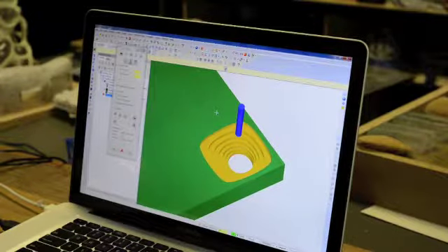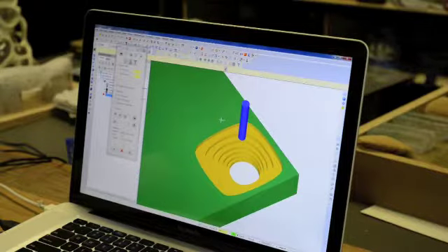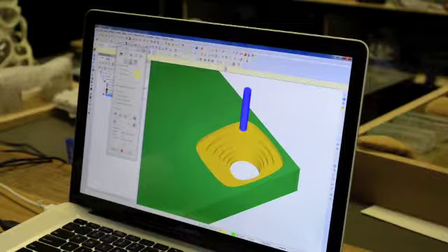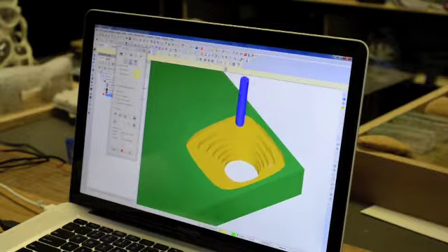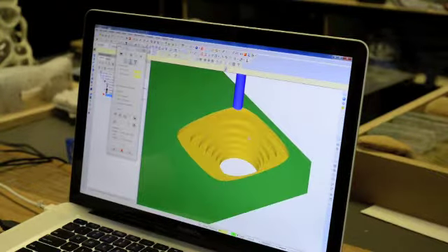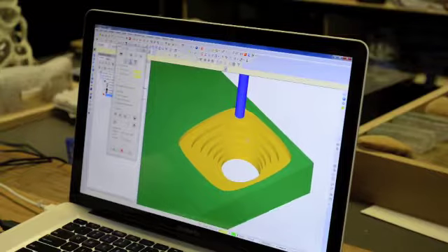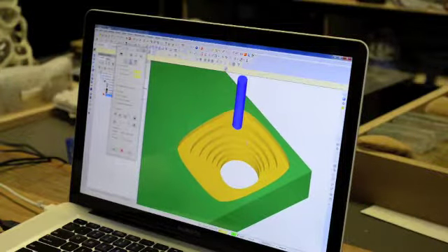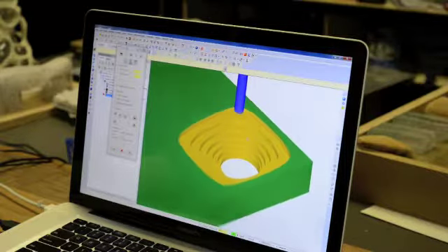Okay, to clear up the mass of stock we had left in the center of the mill, we basically removed the circular containment around the bottom, so we were left only with the square containment at the top. Sometimes when you run the simulation, you'll see that there's issues with material left over, and you may have to retweak your containment areas in order to clear that problem up.